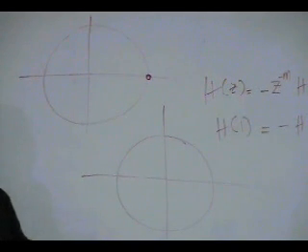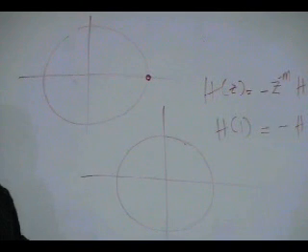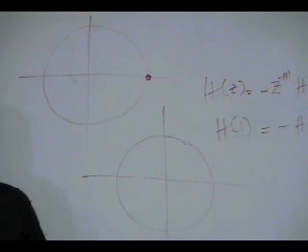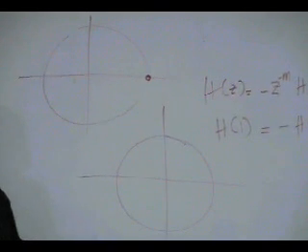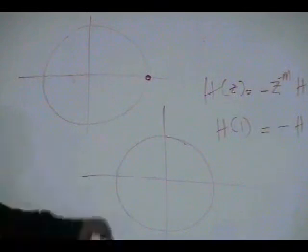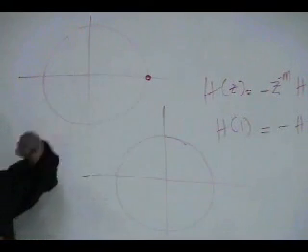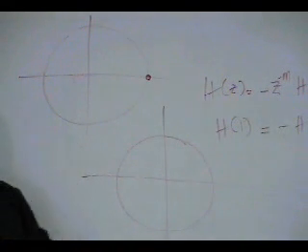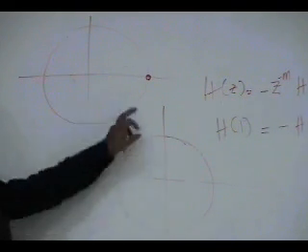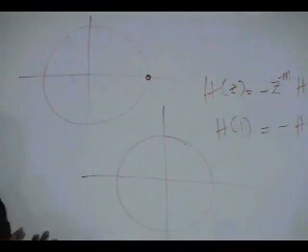So what does it mean? You cannot have a low pass filter as a type 3 or type 4 filter, no matter what. I mean, an anti-symmetric filter can never be a low pass filter, guaranteed, out of the question. Okay, this cannot be a low pass filter, whether it is type 3 or type 4.